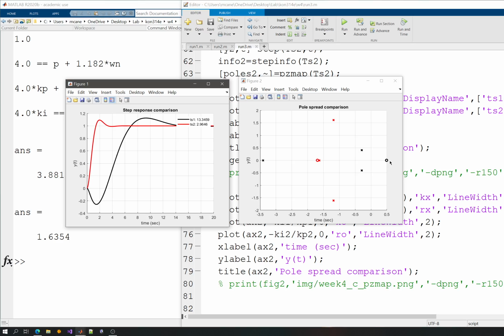So having a zero on the right half plane is not that ideal, but it's not affecting the stability, since the stability is calculated or determined based on the poles of the system, not on the zeros. So the zero affects the system, but not the stability. But the step response, or transient response, or even the steady state response can be affected by a zero.